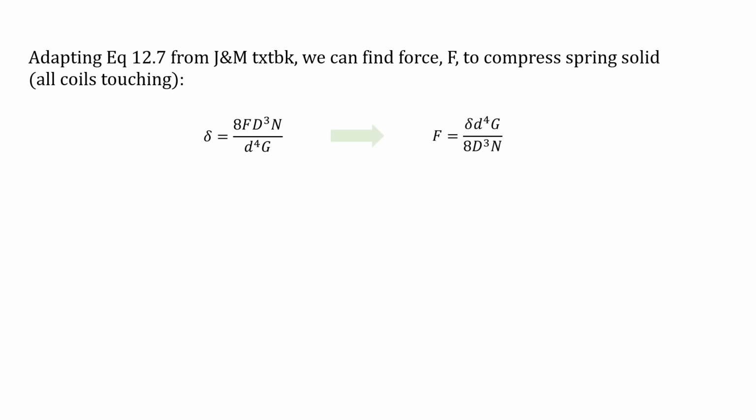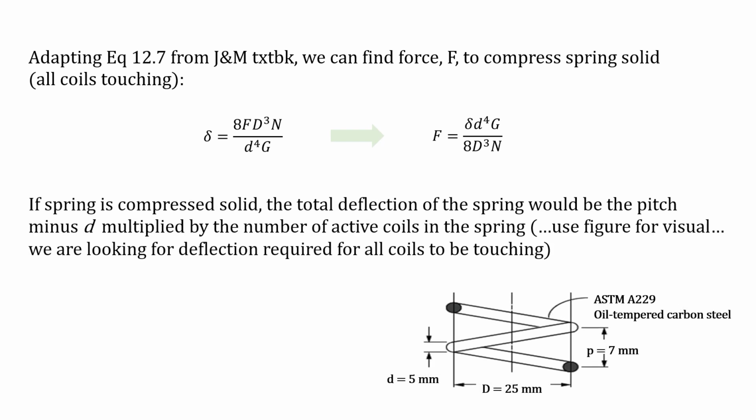We'll notice that we're not given the deflection, we're also not given n, which is the number of coils in our configuration. So in this case, what we're going to do is lump that deflection over n as a single term, because we have some variables and some knowledge of the situation that we can use to solve for that term.